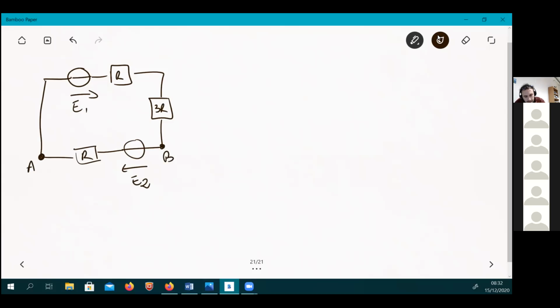The question is, what is the voltage UAB? This voltage is already fixed because I fixed the name UAB, which means the voltage is pointing toward the first letter. So you need this voltage. Know that this UAB voltage is going to be partially E2, but then you need the voltage here, the voltage at the terminal of R. To get it, you need the current in this mesh.